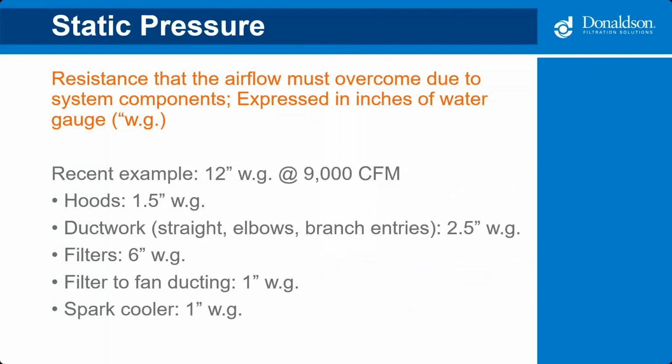Like I was talking about, a critical component to fan design is static pressure. It's basically the resistance that the airflow must overcome due to system components. It's expressed in inches of water gauge, as you see here. When we design a system, we calculate the total system static pressure so that we can size the fan properly.